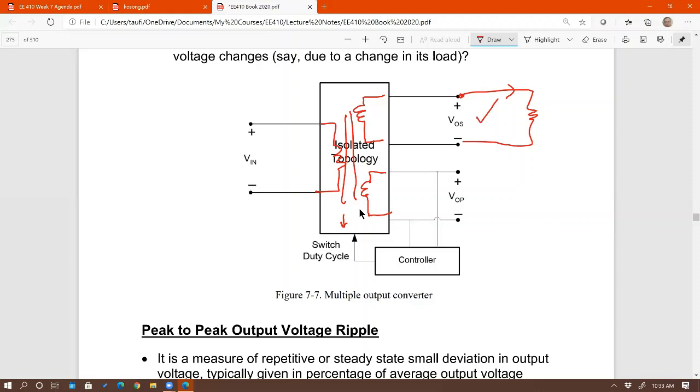Well, of course, V out is going to change accordingly. If I out is getting higher, then output voltage is going to go lower. It's going to drop, right? Now, if that's the case, is there a mechanism to fix this output voltage? The answer is no. There's no feedback, right? So unfortunately, the output voltage will be lower because of this change.